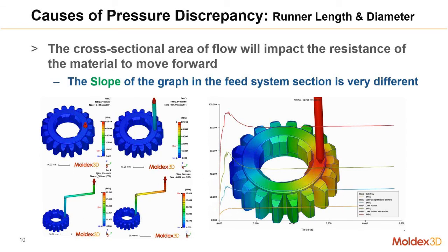Moving from the drop all the way up to the top of our sprue, we get even more of a pressure loss. And then introducing an annulation into the drop here also increases the pressure as well. So like I was just mentioning before, just cutting out the valve pin through our drop here can increase our pressure quite a bit. This is somewhere between 40 and 50% difference.